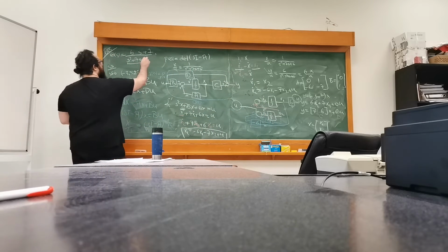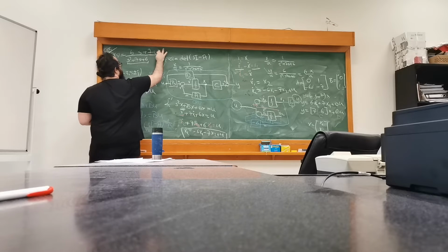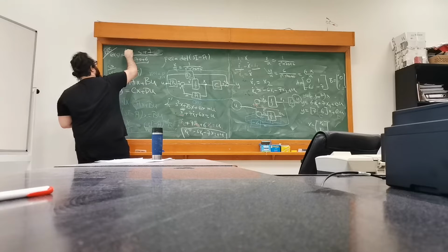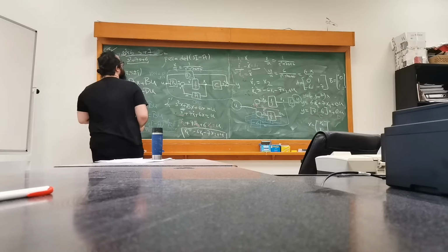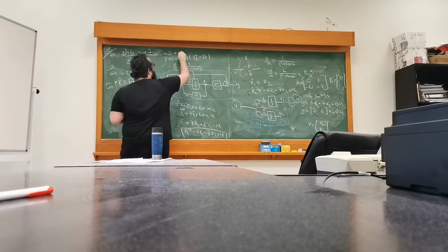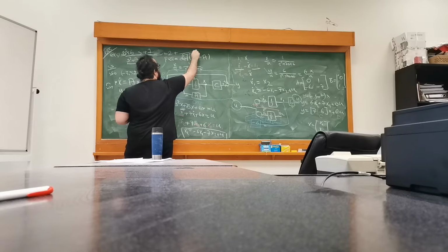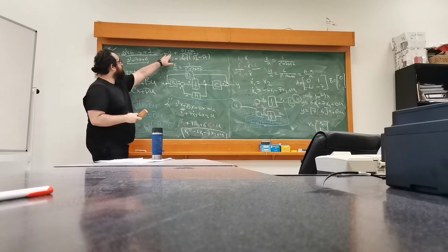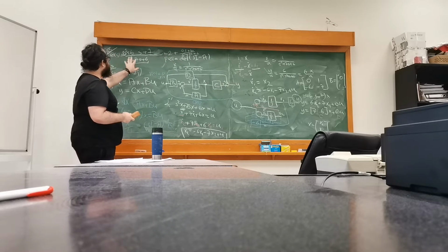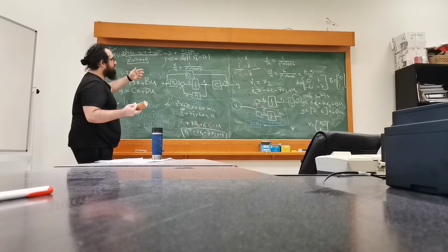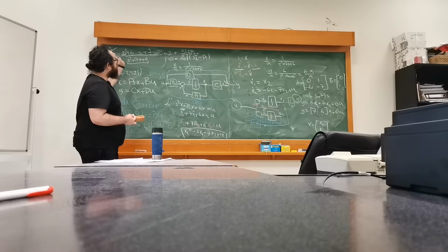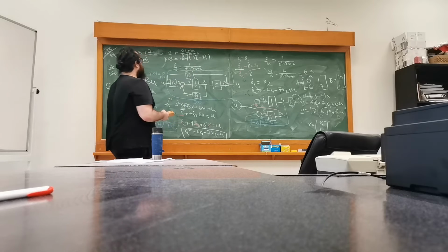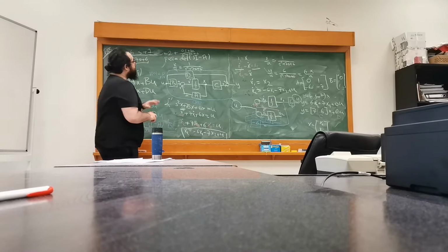In case of s squared, if you have something like this, or if we write here 2s squared plus 6s plus 7, then you have to transform your transfer function into 2 plus as plus b over the polynomial. Why did I write down 2? Because if you divide this, you will see that there's 2 times this polynomial. You have to maybe carry out the polynomial division. You'll see that there is this 2 term here, and then there's the remainder part, the remainder being as plus b. So you have to divide the polynomials, or put it in this form.